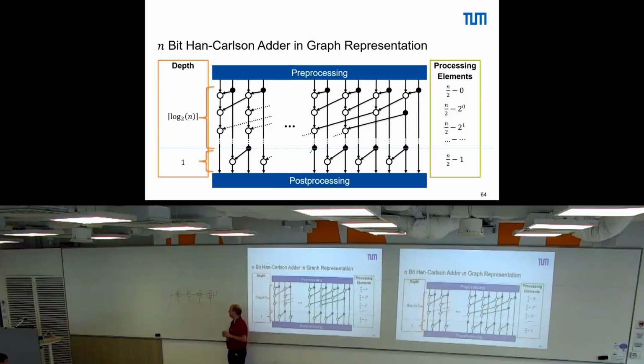Now I want to transform this into a carry save adder. What do I need to do? If I only want a carry save adder by rewiring, I don't need an additional layer. To have something useful at the end, I would need some, but for the carry save adder itself, I don't need that. No, that's also not the adder itself. So yes, in practice, you need a register before and a register after, but you also need this for a ripple carry adder. Yes, same as here. I only want to transform the structure. Exactly. So we remove this connection and have our carry save adder, right?